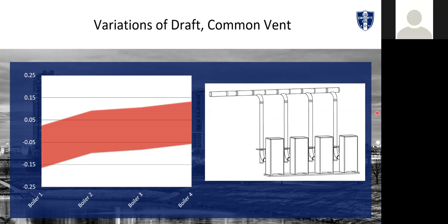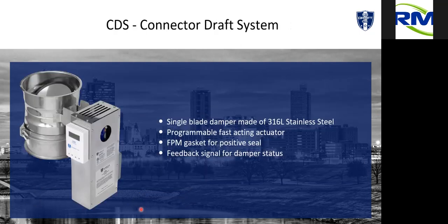And then another one coming in, Jason, from another one of our clients here is, what are the sizes of the CDS dampers that you guys have available? Sure. Those are 4-inch to 16-inch in 2-inch increments. So it's 4, 6, 8, 10, 12, 14, and 16. We did have a request for a 7-inch damper. Sure, we could do a 7-inch damper. It's basically going to be an 8-inch damper with 2 reducing bell fittings, because our roll dies just don't go down to 7-inch. So it's either a 6-inch or an 8-inch. So that covers those.